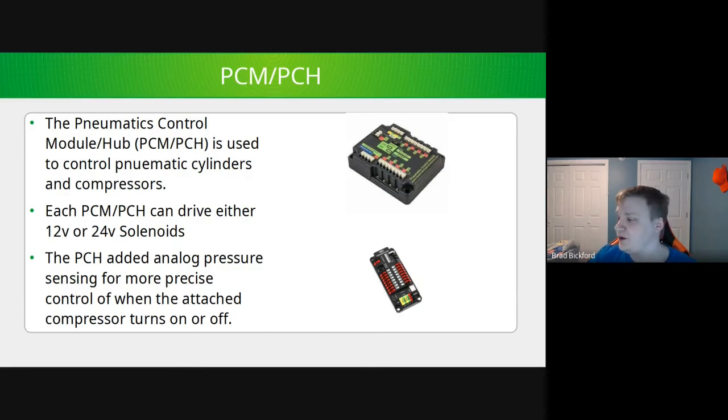And the reason why you'd want to do that is simply because starting and stopping a compressor many times tends to use more power than just starting it once and letting it run. It's because spike amperages tend to be exceptionally high compared to just running it consistently for a long period of time.